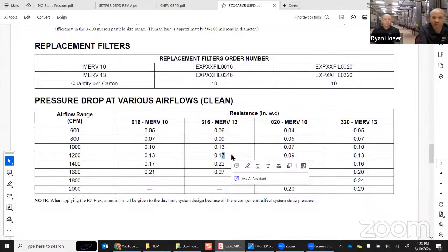I don't want to call any brands out by name, but there's a specific brand you can pick up at Home Depot that has all these high pollen filters, but they're all 1-inch, because people buying things at Home Depot literally walk in there with the filter in their hand and go to the shelf and find the one that matches the one that came out of their basement. They need one that says 20 by 25 by 1, and that's the one they're going to buy no matter what anything else says. A 1-inch high MERV filter is usually a problem.